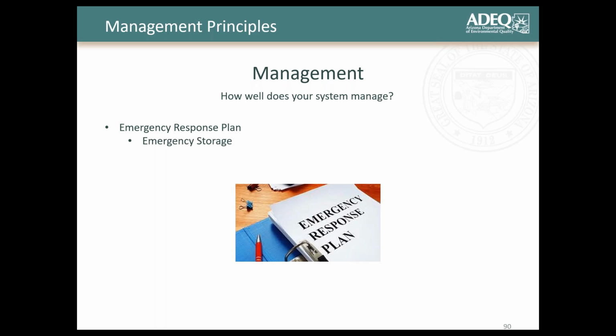I think this is the last one. And of course, make sure that you have an emergency response plan, right? Make sure that you're ready. You have a plan for all of these potential emergencies, whether emergency storages or emergency responses. If a lift station goes down, right? We used to have big containment ponds in certain lift stations. Do you have that available to you? How much detention time do you have in your sewer system itself? Those are things and calculations that you want to keep in mind. Also, an emergency response plan for chemical responses, right? So all these things matter.